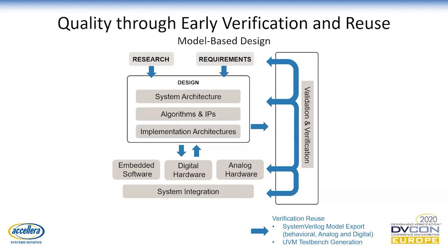So for instance, one way to use this is, if you want to generate a 5G compliant waveform, that's very easy in MATLAB, while doing it in SystemVerilog might be quite tricky, right? So you can do it in MATLAB and integrate it in your digital test bench, for instance. Another way to use this in a smart way is you can take analog models and integrate them into digital EDA simulators, so at RTL level as a test bench component. So it can help you bridge between different domains, analog and digital.